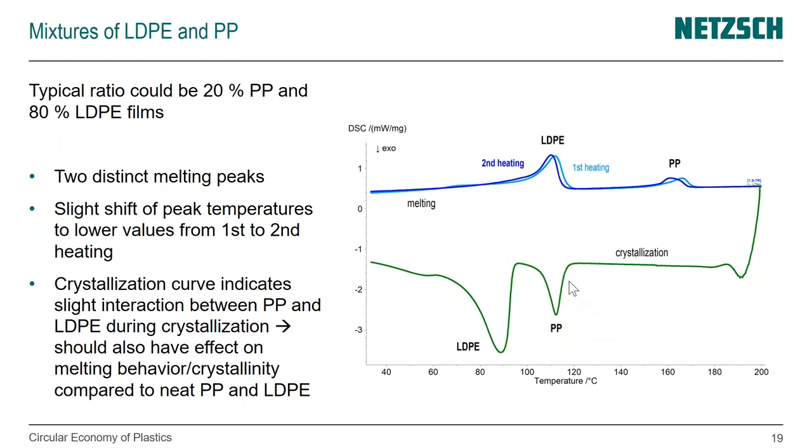So it tells us the lower the molecular weight, the faster the crystallization happens and the higher the crystallization temperature. But it's not a straightforward method. You would need, again, something like a calibration. You would need the molecular weight of different materials, and you would then be able to correlate that to crystallization and melting behavior.